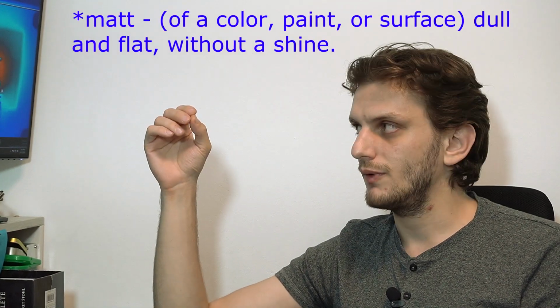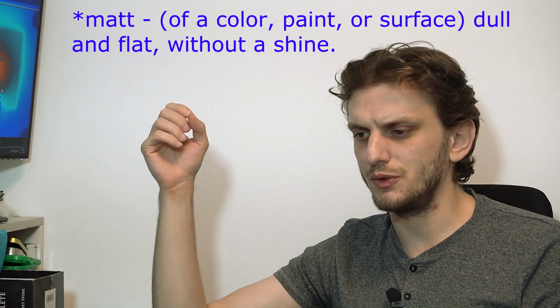And for this, a surface finish that should help the most would not be black paint, but black matte paint. Matte, I don't know how it's pronounced, so not a glossy finish, but rather a non-glossy finish that should be able to radiate much better. But of course, this has to be tried out, so depending on the manufacturer, these paints might have different properties. So it's not as simple as saying, oh yes, black paint is good. No, you need to try it out, see what your local supplier can offer.